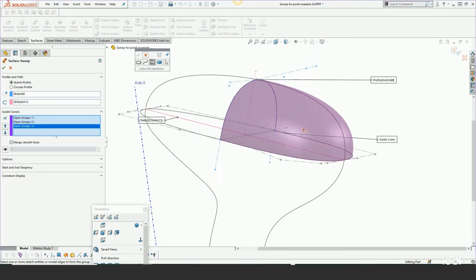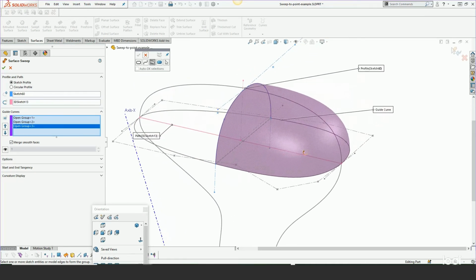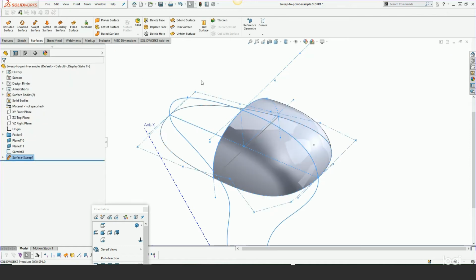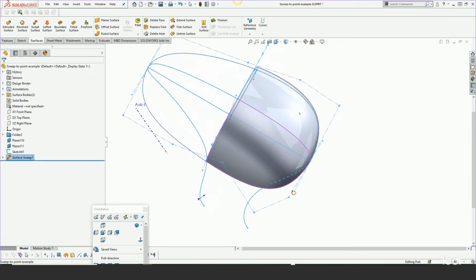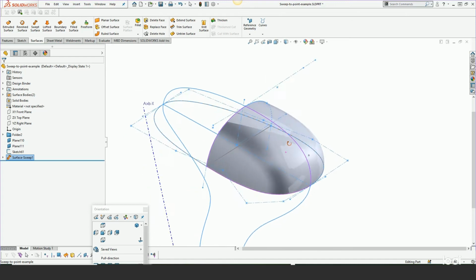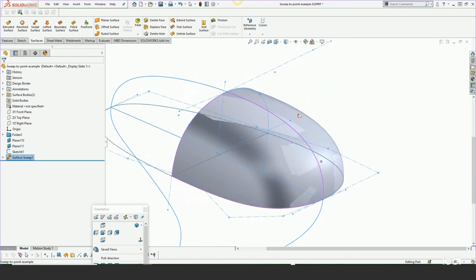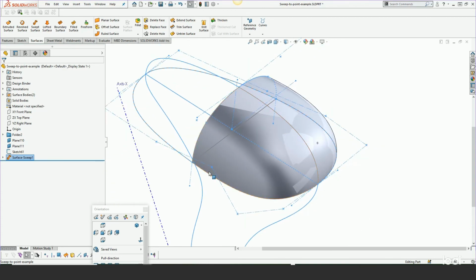So now what you can see is a very powerful result, and that's the fact that SolidWorks Sweep is able to sweep down to an infinitely small point or 0 with the path. So if we complete that, this is what we get. Very high quality surface. I prefer to use this solution over boundary because you get a higher quality surface. This surface will never inflect because it's being created conically as it moves down the path and then is directed